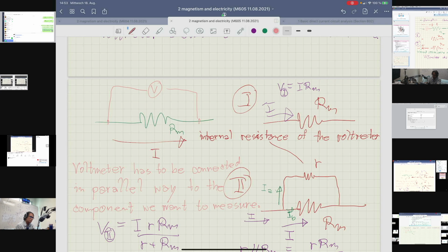An ammeter should always let the current flow without any obstruction. The galvanometer can be made into an ammeter by connecting it in parallel with a small resistance R, capital R, which is known as the shunt resistance. Let's take a look at this example. We will see what happens.